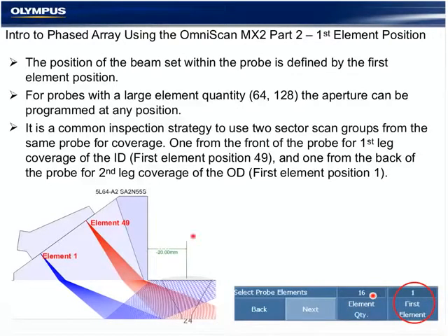In this case, this probe has a 0.6 millimeter pitch. So if I use 16 elements times 0.6 millimeters, it is going to give me a probe aperture just short of 10 millimeters. The two parameters I'm seeing here are simulating a 10 millimeter by 7 millimeter conventional beam. And we can manipulate it with a beam tool plotter like you see here, or directly into the instrument.